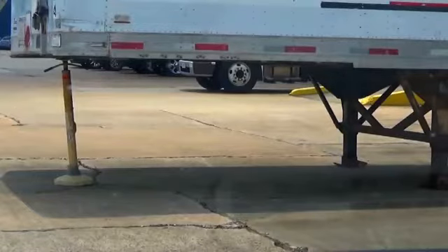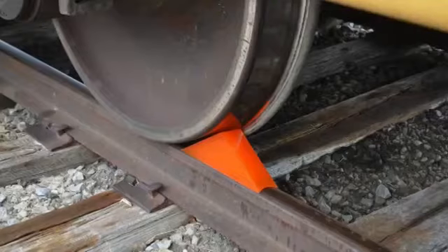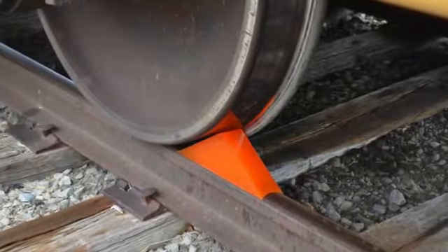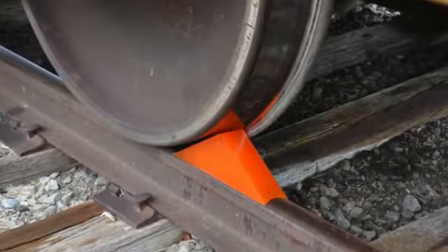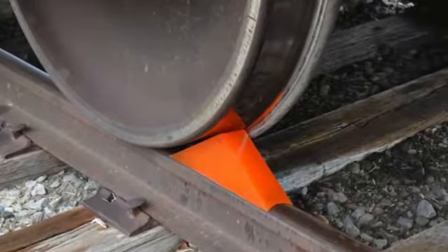The use of fixed jacks may be necessary to support a semi-trailer during loading and unloading when a trailer is not coupled to a truck tractor. Wheel stops or other approved positive protection must be provided to prevent railroad cars from moving during loading or unloading operations and while dock boards or bridge plates are in position.